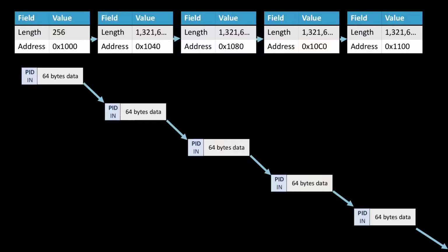Now, if we're able to start applying voltage glitching or clock glitching, if we're able to glitch something in the system and corrupt that length, then what we'll get, instead of those nice orderly transactions where we send 4 individual packets to, let's say, send out that configuration descriptor, is a length that is potentially much larger, which continues to transmit and transmit and transmit well beyond when the device should have stopped. And if you have a device with a DMA controller that works like most of them do on microcontrollers, it will continue not just out of that descriptor's location in RAM or ROM, but continue throughout the entire memory map until that length field is brought down to 0.